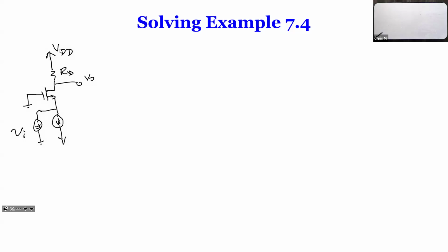The first step is to take out the MOSFET and draw the T model for the MOSFET. Step 2, we connect all the components. Step 3, we solve the problem. The MOSFET is right over here, so we take out the MOSFET and draw the small signal equivalent circuit model. This is our gate. In the future, you should always do this: look at the MOSFET, draw the small signal model.